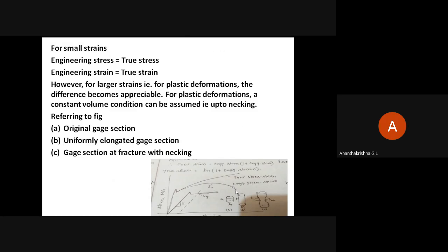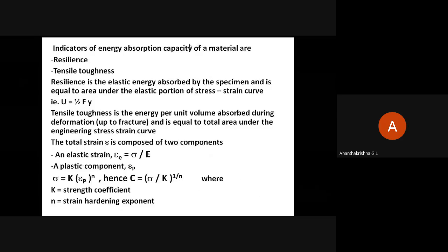Toughness. Exactly. The tensile toughness is given by energy per unit volume absorbed during deformation, and is equal to the total area under the engineering stress strain curve.